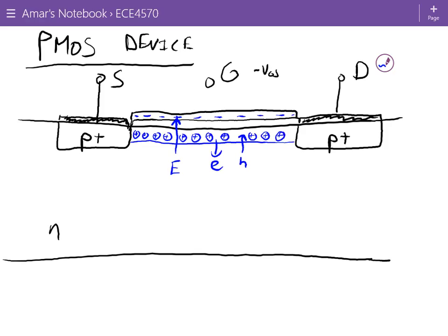And then on top of the depletion charge, the second effect is that you're pulling in the holes. Those are the minority holes that exist in an N-type semiconductor. And those holes collect in this region up here, just right underneath the surface. And those holes are mobile. The region where those holes collect is called the potential well, and that region becomes p-type. And when this becomes p-type, now you have a connection between the source and the drain, which is also p-type. So it's exactly the same as an NMOS device, just with the polarity switched.